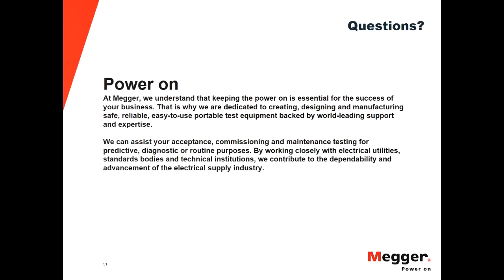Yes, and this again goes back to a couple of questions ago when we talked about taking the downtime or pausing the test for 6 minutes. When you take the cells out, you need to adjust the end voltage based on the number of cells that you have taken out. And yes, our software allows you to do that at any point during the test. You can change the warning limits or the stop limits. That can be done while the test is on.